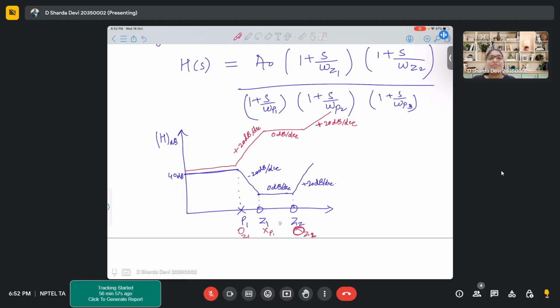Thank you. So in the Bode plot, the plot that you represent finally represents the effective value of slope. Here effectively it will be 0 because plus 20 is nullified by minus 20. So you will report the effective values. It is a very big mistake. It is actually a silly mistake, but people do make mistakes like this.